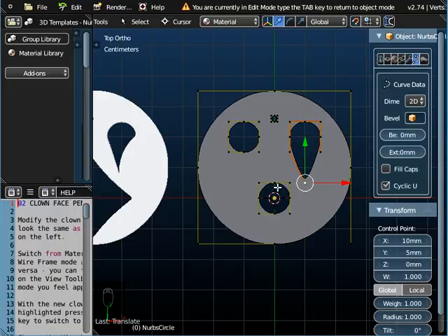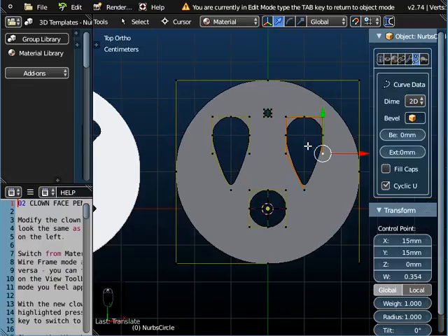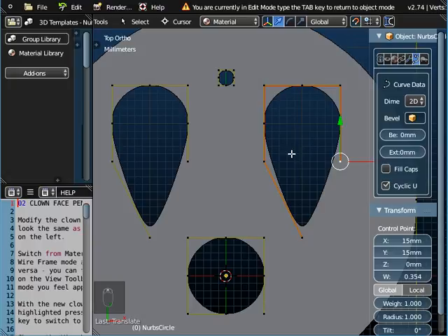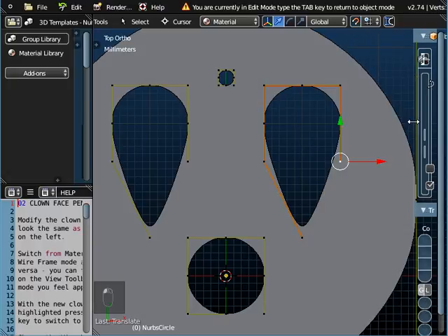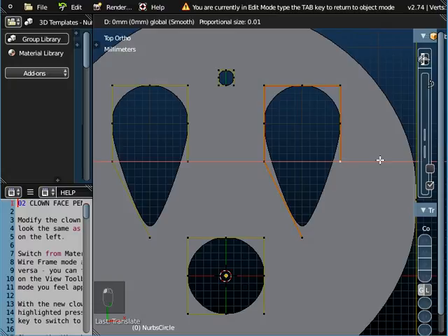So switching on the snap forces you into a particular movement. If I click on this one here now, that will also snap to exactly the same location as this point, because it's moved exactly 1 centimeter. Now there are times when you want to move things less than centimeters, so we'll select this point here, and you have to zoom in. I'm scrolling the center mouse button until the millimeter grid is displayed, and you can then move it 1 millimeter at a time.